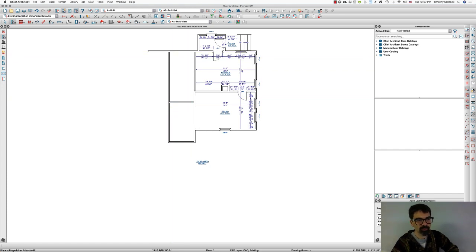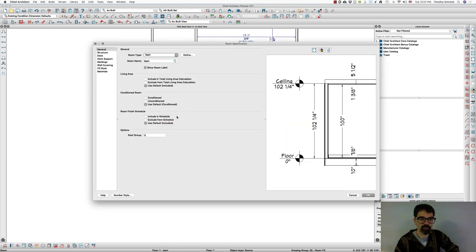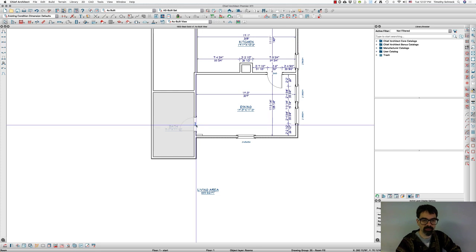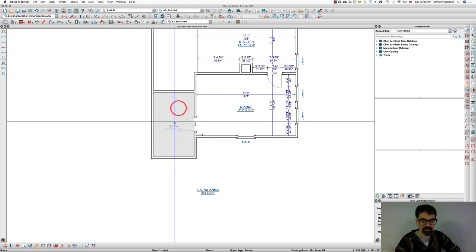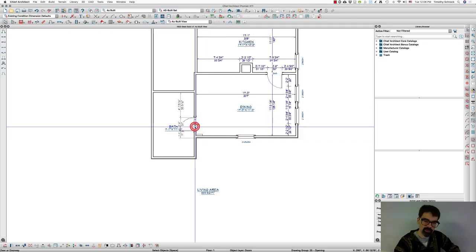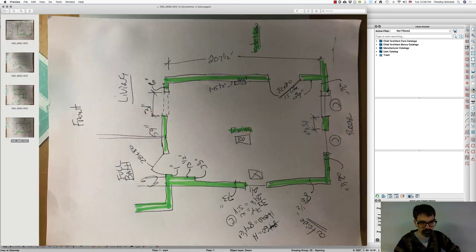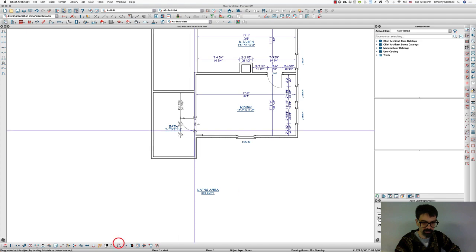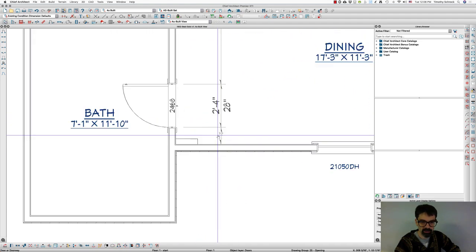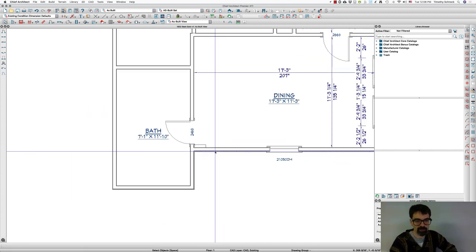And then we're going to draw this bathroom in here. So the reason I drew this as a room is twofold. One is if it's an interior room to room, the door will show as an interior door, and I can give this a label called bathroom, full bath. This is 28 by 80 door. It's going to flip that direction, and it is going to be 1 inch off of that, so 4.5 off of the main wall.